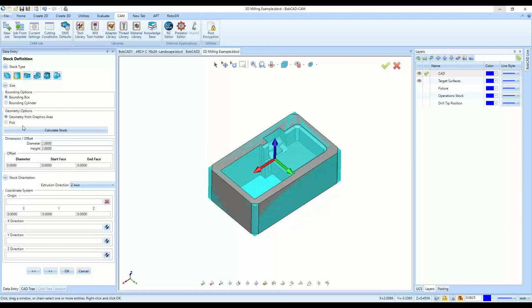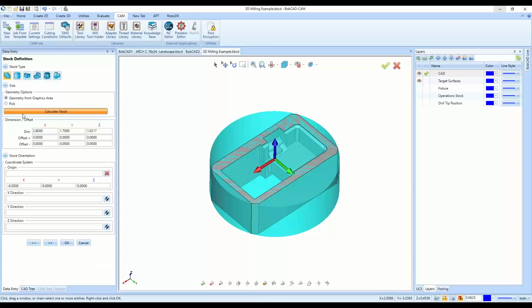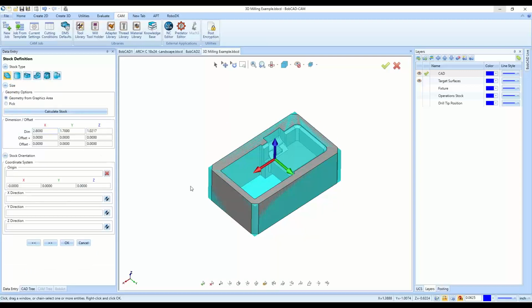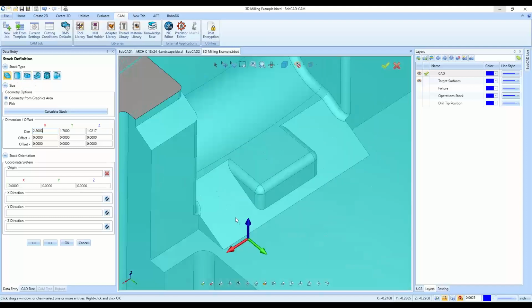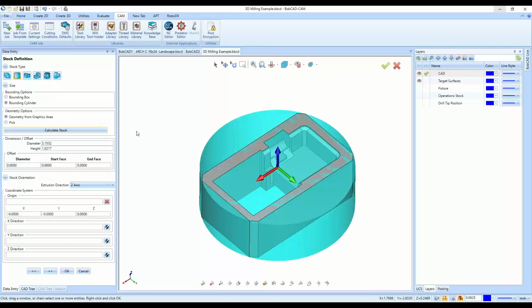That's where I can change it from rectangle to cylindrical stock type. You don't get these options in the Mill Express, only in the Mill 3-axis Standard and the Mill 3-axis Pro. You only get rectangle, where you can change the dimensions here. It doesn't really make a difference for the Mill Express, only because you're doing 2.5-axis machining like we went over last week. This one's going to be 3-axis machining, where we can follow along surfaces like these tapered walls here. And then we can also define our stock, letting the software know how much material is exactly remaining to get down to our finished 3D model.